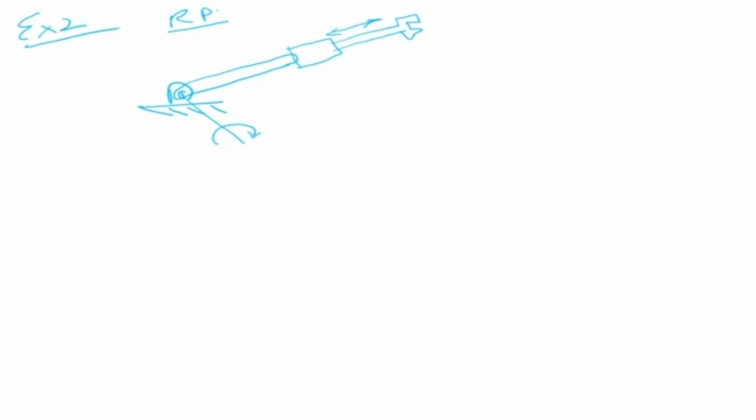Let's put our DH parameters. I can put my z0, z1 here. So x0 is there and x1 is here as per DH. This angle is my theta 1. Let us say this is my m. L1 is the distance from here to here. This is a prismatic joint, so it can move back and front. Let me say this full distance from here till here is my d2.